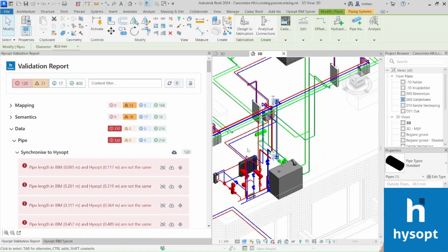Because we just adjusted the diameter in Revit, the lengths of the pipes were readjusted because the bends, T-joints, etc. were resized. This is a perfectly logical result, and also a great example that a calculation model and a 3D model will always affect each other, and that it's an iterative process to fully align and optimize them.